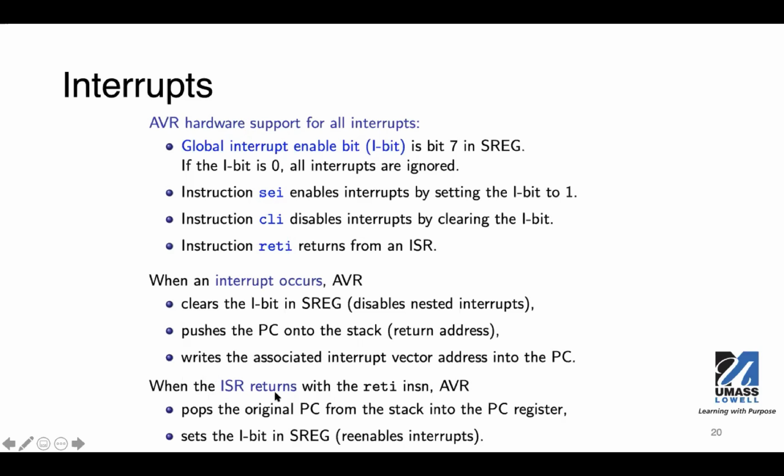When the interrupt service routine finishes, the last instruction will be a RETI, and that will let the AVR processor pop the original program counter from the stack to the PC register, and it will then set the I bit to 1 to re-enable the interrupts.